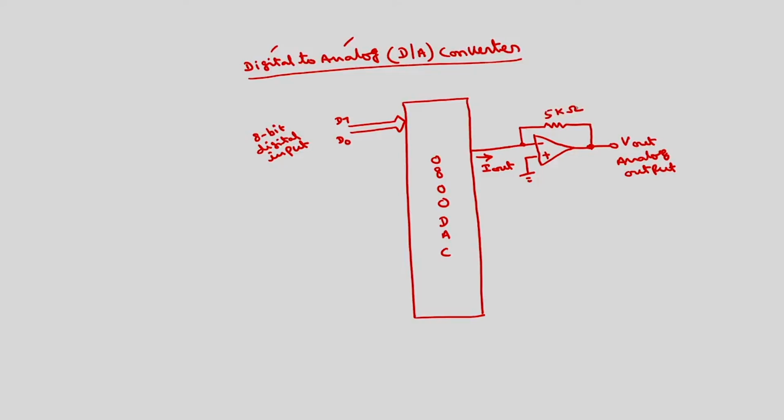This is analog output. And there are several pins, like there will be two reference voltages. If I want to use only one single polarity reference voltage, the other polarity has to be grounded. You have to connect through some resistance. Depends upon this resistance, the I reference current will change. So, this pin is V reference minus. We are grounding it.